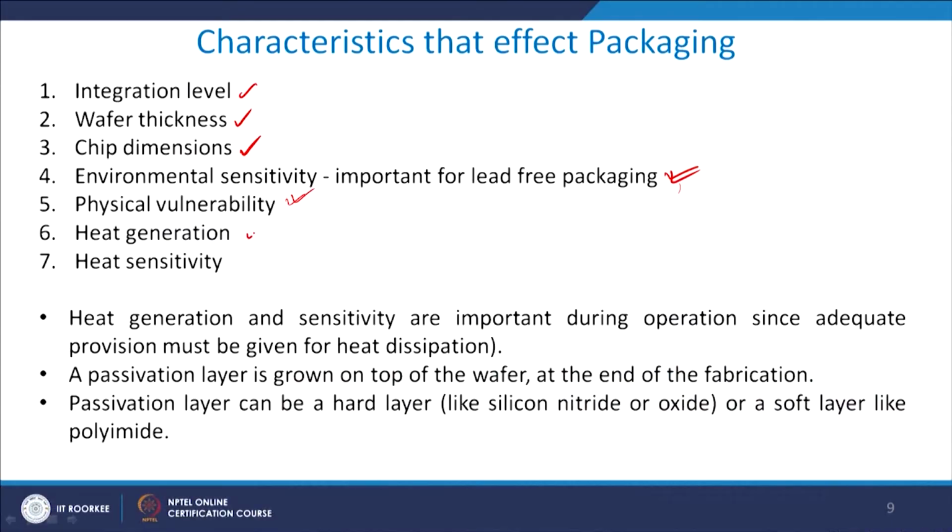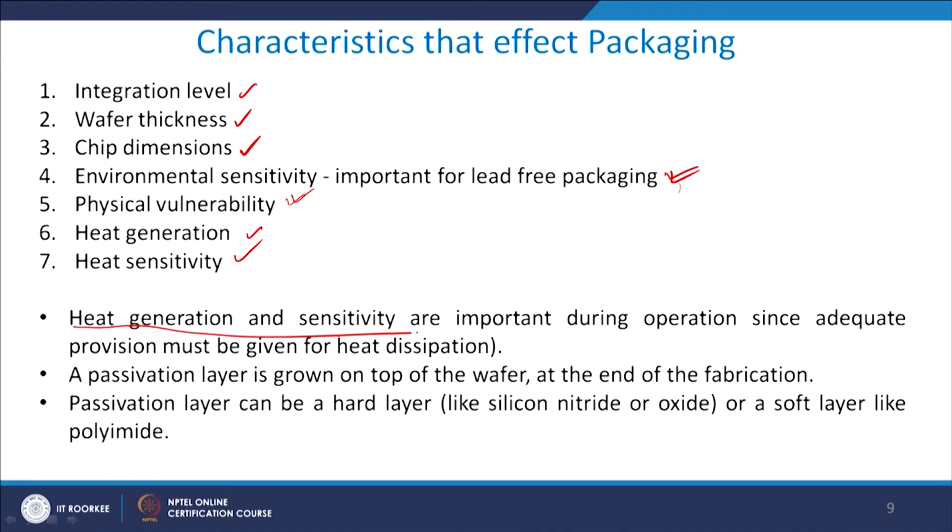Heat generation and heat sensitivity are two important points. For example, all mixed signal blocks and analog blocks generate very heavy heat, but we should ensure that the package behaves as a very good heat sink and removes all the heat even before it comes to the surface. Therefore, as I discussed with you, heat generation and sensitivity are important during operation, since adequate provision must be provided for heat dissipation.